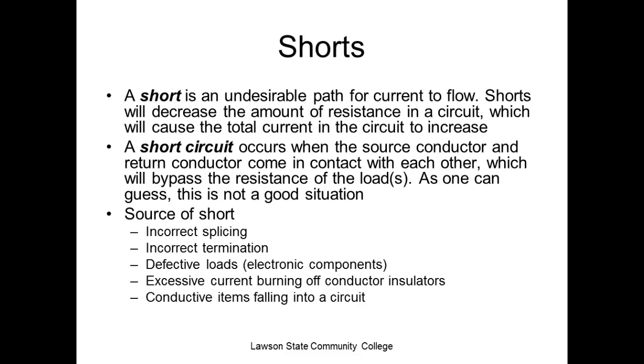We got a deliberate short circuit over, I call it Big Bertha over here, this big old DC power supply, we're going to show you all a short circuit. Short circuits are caused by incorrect splicing, incorrect termination, defective load, excessive current burning off the conductor's insulator, conductive items that fall into the circuit. So if any of these happen, there's a good chance that we would have a short, but not necessarily a short circuit.